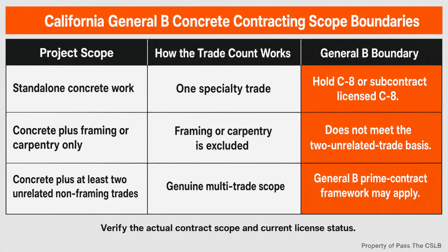The general B contractor does not need to become the nozzleman to supervise the work well. The supervisory responsibility is to recognize that shotcrete quality is created during placement and can become concealed almost immediately. Conventional cast-in-place concrete is placed into forms. Gravity and mechanical vibration can help consolidate the material around reinforcing steel. Shotcrete is pneumatically projected onto the receiving surface. Its consolidation depends heavily on the impact, velocity, and the spray angle at the moment of placement.